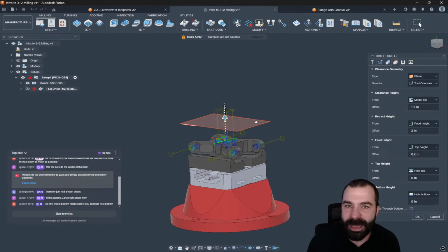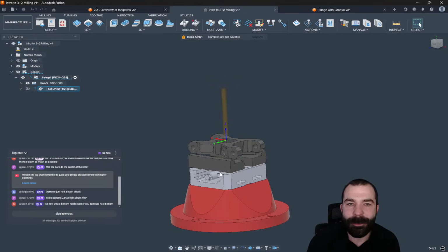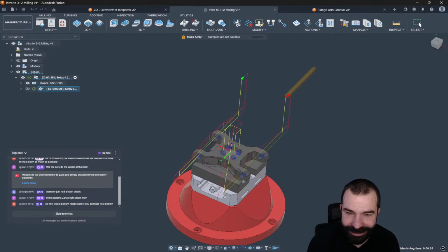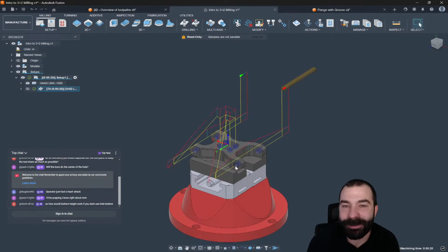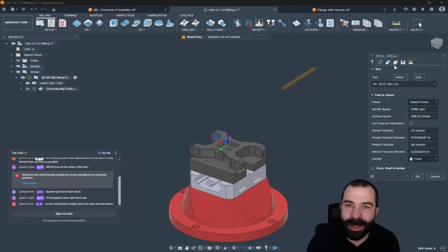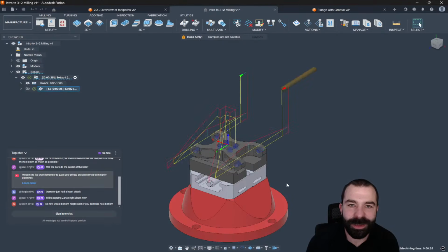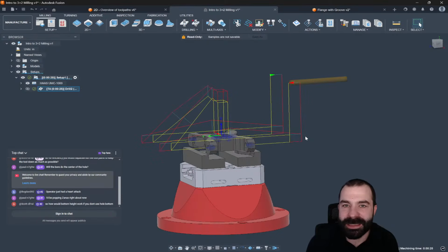But when we shifted back to 5-axis, we went back to a plane structure. And now we are getting some extremely different results again, right? So I want you guys to just pause for a moment. And when you think about this, is my tool based on that plane from tool orientation, right? So again, we're automatically orienting our tool, where we could change this if we wanted. But each one of those tool paths is going to start from whatever that distance is on that plane. And simulating this, you'll notice, again, there's going to be quite a lot of pucker factor.